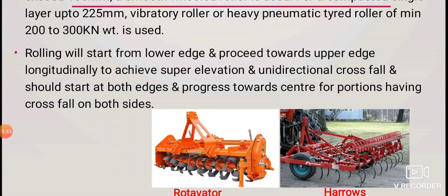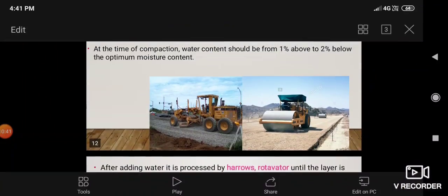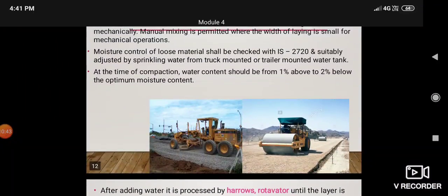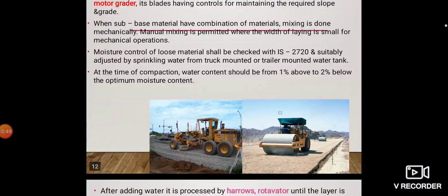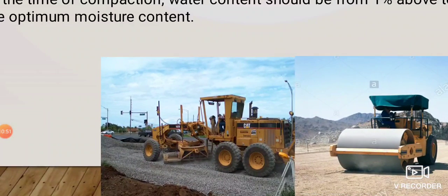This mixed material is again spread to the desired thickness, grade, and required camber, and the motor grader with its hydraulic connections needs to spread it properly.